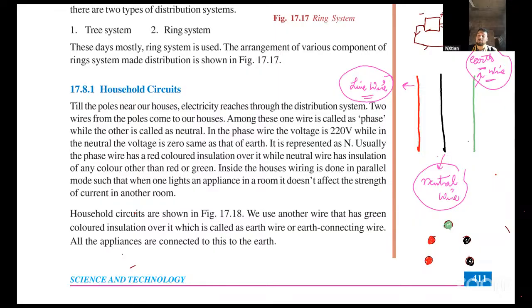Yes, David. Yes, Joshua. Won't you get a shock if you do that? Because the resistance of the tester is too high. Too high means the current will flow very little, so you will not get any shock.